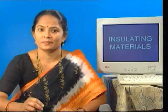The insulating materials offer very high resistance to the flow of electric current. They require extremely high voltage of the order of kilo or megavolts to send a few amperes of current through them. In ideal insulators, static electric field penetrates uniformly. Insulators are used primarily for storage of electric energy as in capacitors and are known as dielectrics, but when used to prevent the leakage of current to any undesired conducting medium, they are known as insulators.